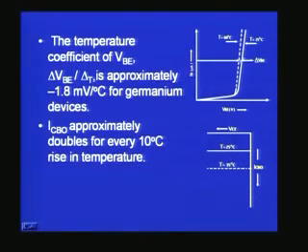So there are germanium and silicon thermometers designed based on this principle, that for a given current IC flowing through the diode or the transistor, you can have a continuous variation of about 2 millivolts for every degree, and so if I can amplify and then read this, I will be able to evaluate the temperature. Therefore this can be used as a temperature sensor, which is also one of the applications we can think of.